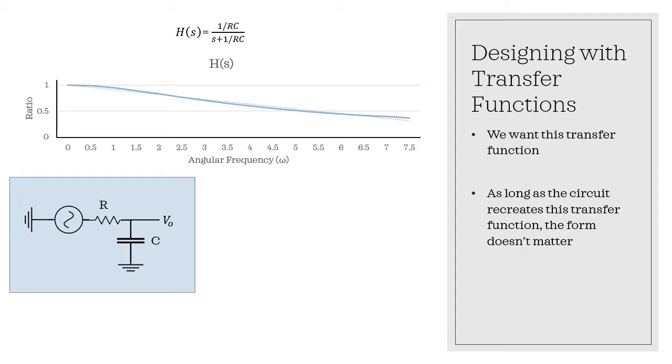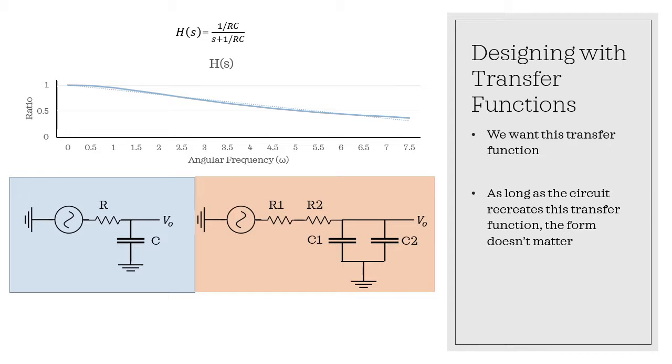Great, this is a very simple, easy to understand, straightforward circuit. What if someone approaches you with this circuit? Twice as many components. Looks kind of similar, but does it do the same thing? It does. It does exactly the same thing. Because those two resistors right there, you add them together, they're in series to create one equivalent resistance. Capacitors in parallel give you a simple sum of their capacitance. And then the voltage output is in the same place, above the capacitance between the resistor.